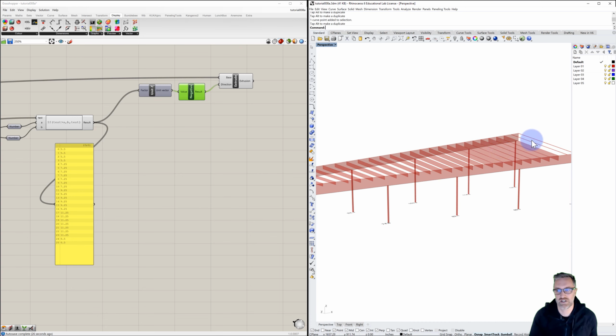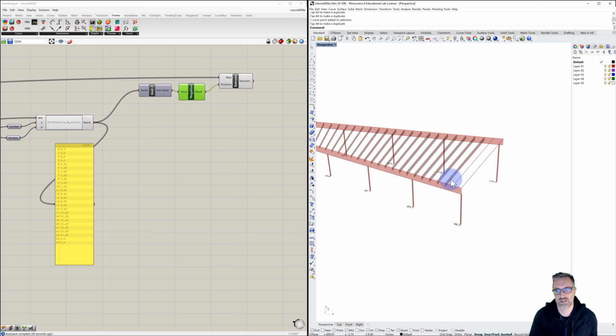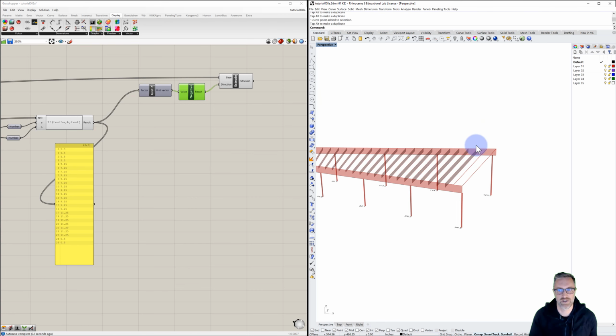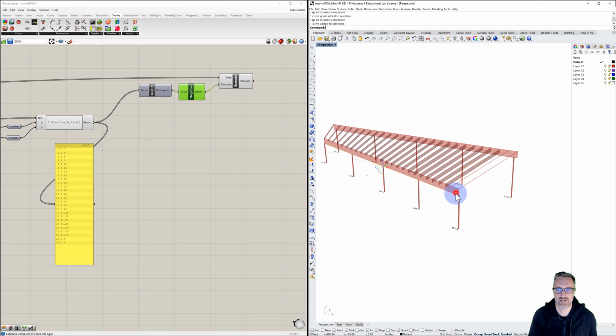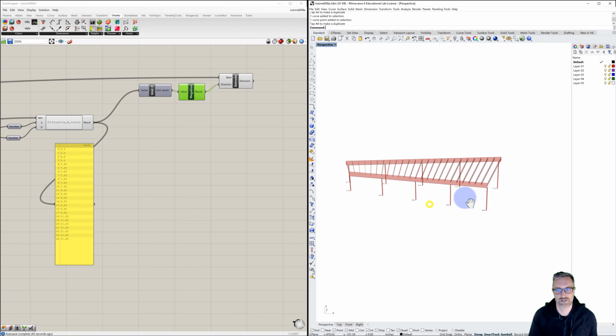And then the last bit that are too long for the allowable lumber that we have available for the rafters, I just had become a small value so that I knew that I exceeded the number. And then what that'll allow me to do is to move my girders a little closer together.